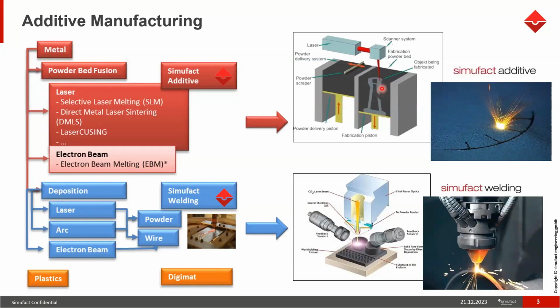There will be a part getting manufactured over here, layer by layer. Each layer will be a very thin layer of material, around 30 microns to 50 microns, laid by the recoater to perform this operation.